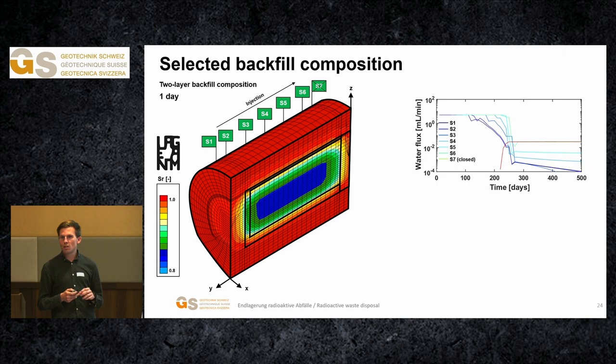And for this final configuration, we can also take a look at the fluxes in the injection lines, where we can see that we have initially the progressive activation of the different injectors, and then we have a slight decrease as the saturation of the backfill progresses, finally leading to residual values of fluxes that are in equilibrium with the fluxes that is computed at the EDZ, through the EDZ.